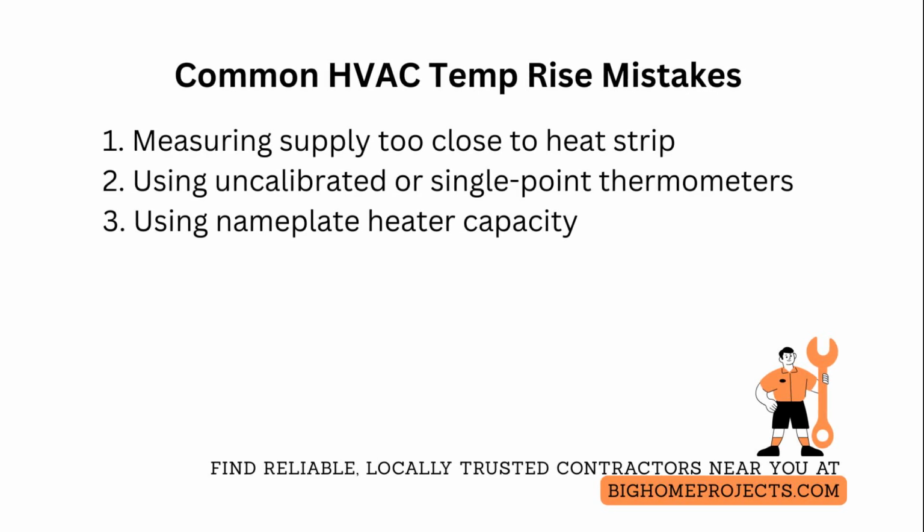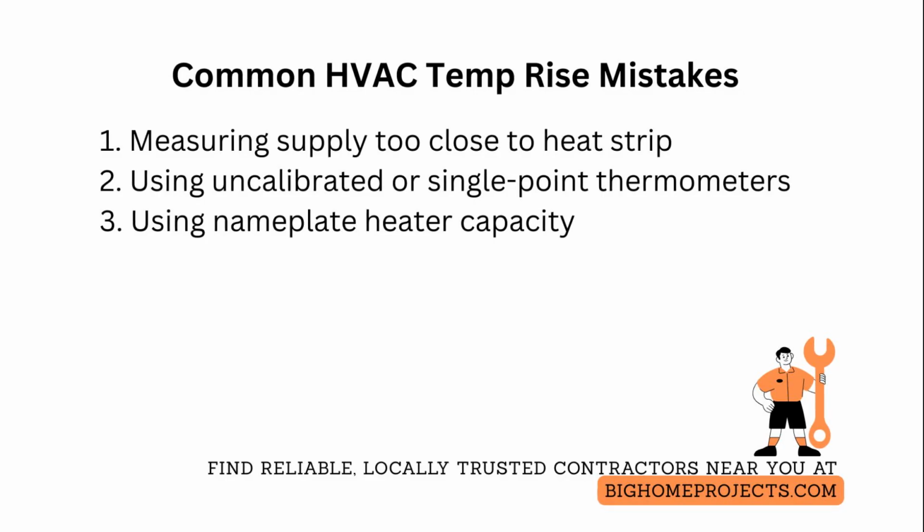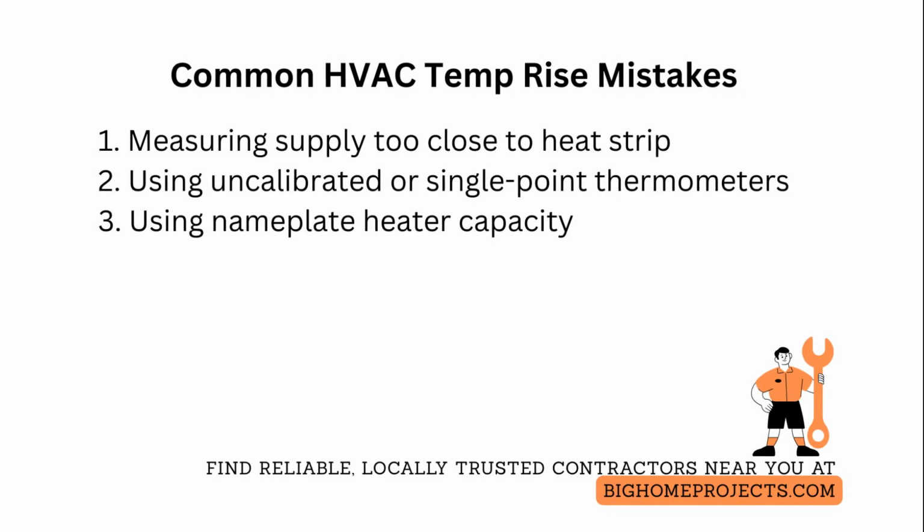Another frequent problem is using nameplate heater capacity instead of actual sensible heat output, which skews the CFM calculation. Fix it by measuring actual delivered heating output or using manufacturer sensible heat curves, and correct for latent loads.